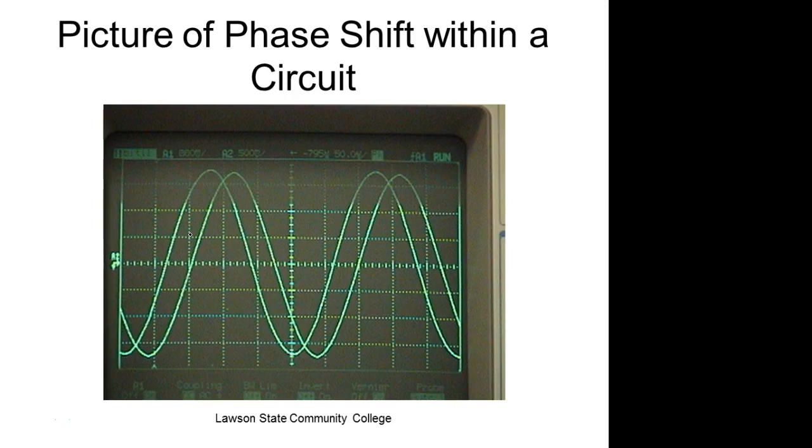Those are capacitors, and they're in there to help do away with the phase shift. Substations have electronically managed the phase shift. They usually have banks of capacitors that they automatically switch in, depending on the power factor, trying to get rid of the power factor.